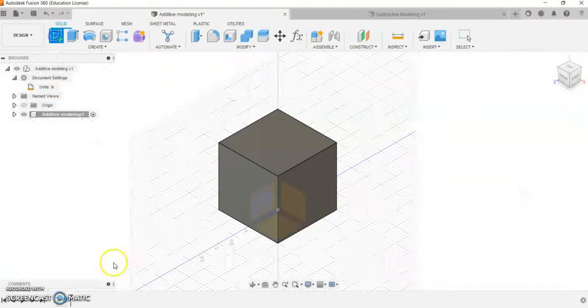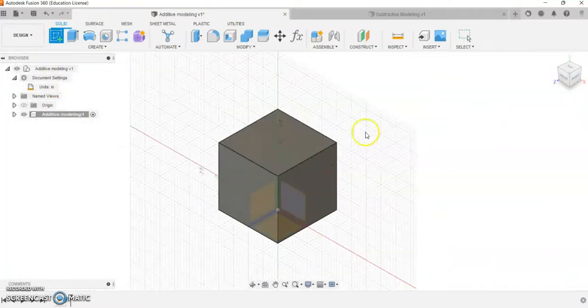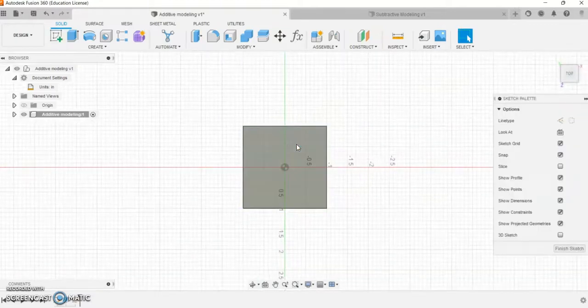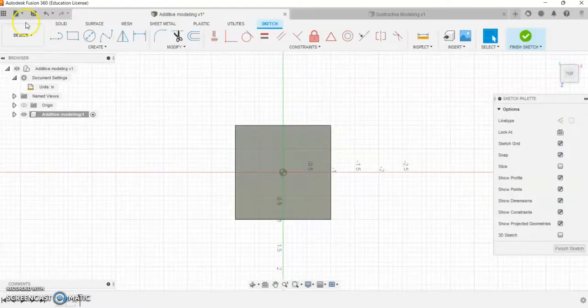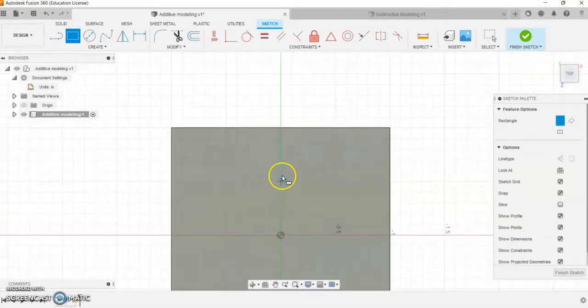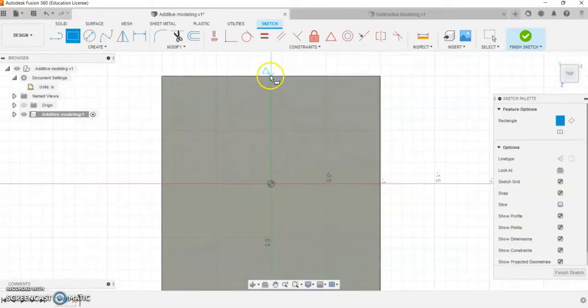So what I'm going to do now is create a new sketch on the top. Notice how when I hover over it, it becomes a light gray. That's what I want. And now I'm going to create a 2-point rectangle. So if I zoom in, you see how when I go up to the top, it snaps to it first of all. That's one thing. But then when I hover over the center of it, that's dead center right there with the triangle. That's what I'm looking for.